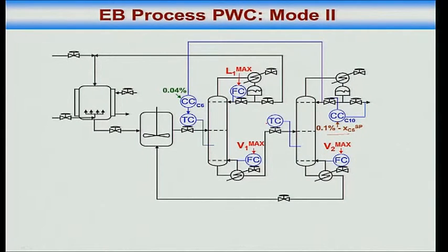It's a stabilization issue. What do I mean by stabilization issue? If I don't control this temperature, I can have a situation where things will drop down and accumulate, they'll just keep dropping down. If I am making more ethyl benzene in the reactors, then I can boil off in the second column. Where will that ethyl benzene go? It will drop down and keep circulating around in that loop. Yes or no? I don't want that. That's a stabilization issue. That's like a level building up and up and up. It's not a level, but so I put a temperature controller there. That's a stabilization loop. Okay.